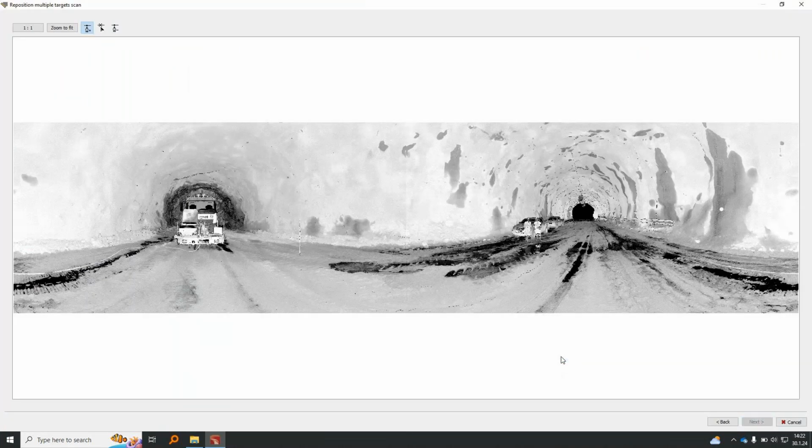And this target pick screen has been improved. It now opens in full screen mode. To pick a target, we have shortcuts for adding a target, moving a target, and deleting a target. We also have a zoom extents shortcut, which is Z, and we have a zoom window. Typically you can pick these 3 in a matter of seconds. If you were just doing it yourself and not explaining, you could do it in 10, 15, 20 seconds, no problem.